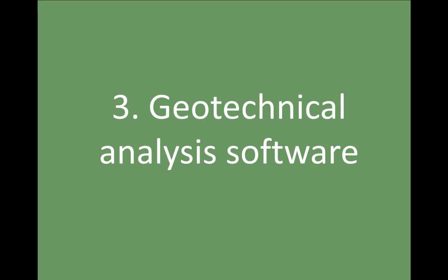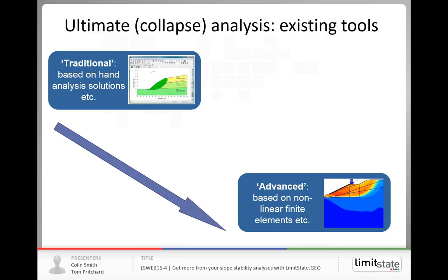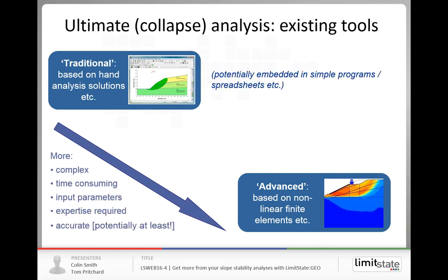Now, just taking an overview of geotechnical analysis software, if we survey what's available, on the one hand, up in the top left-hand corner, we have those that are based on conventional approaches, such as a method of slices, and they do a pretty good job, specifically for slope problems. At the other end of the scale, on the bottom right of the screen, we could be using complex finite element analysis, which can model any problem geometry and complex soil behavior, but typically requires a lot more time and expertise to use.